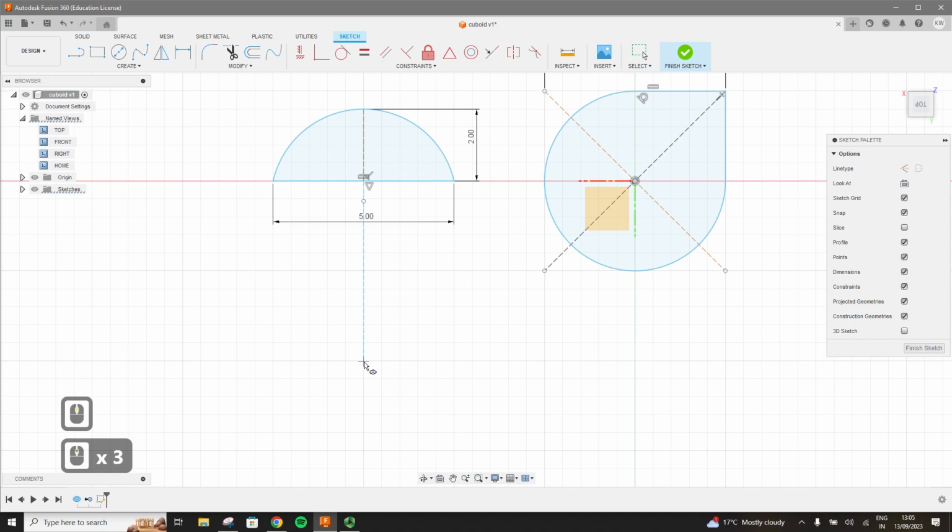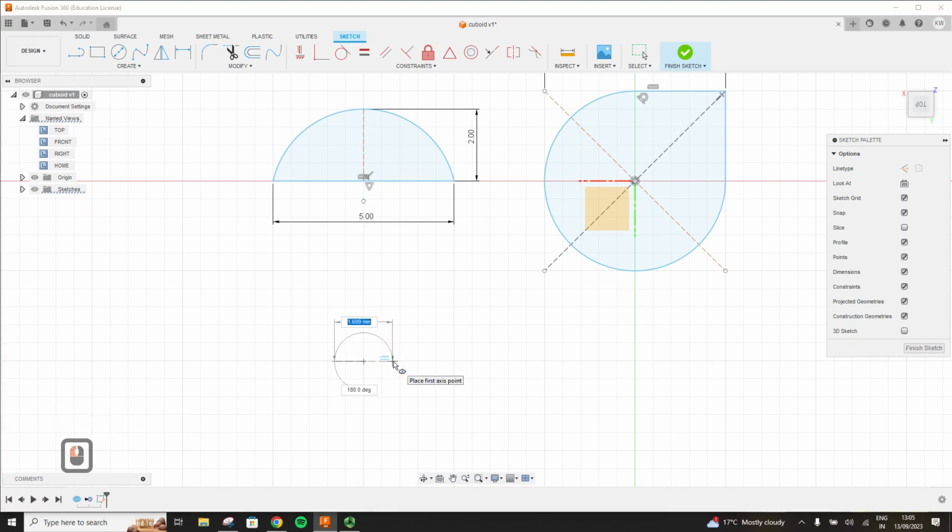So I'm going to click here and we are making an ellipse. I want you to define the first axis, or the dimension of the ellipse. Let's call it 5 mm. As soon as I type 5, without clicking anything yet, I can still control the other value. The two values that I can control while drawing an ellipse are the dimension and the angle of that axis.